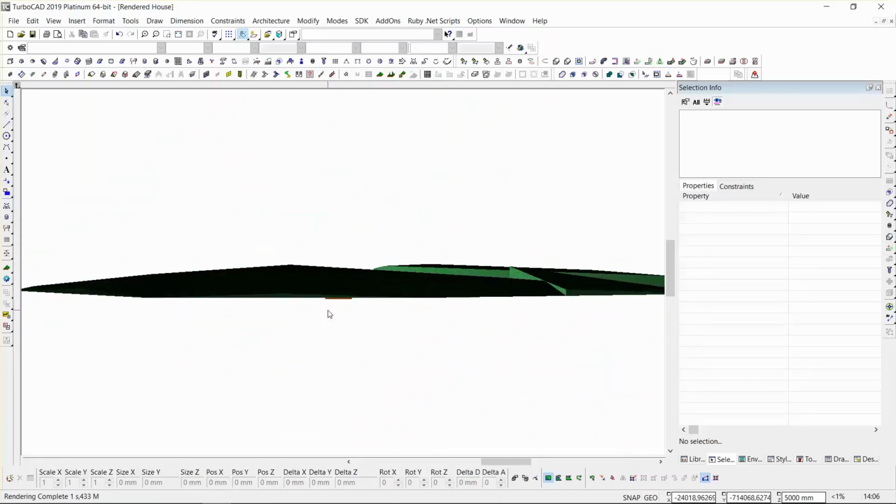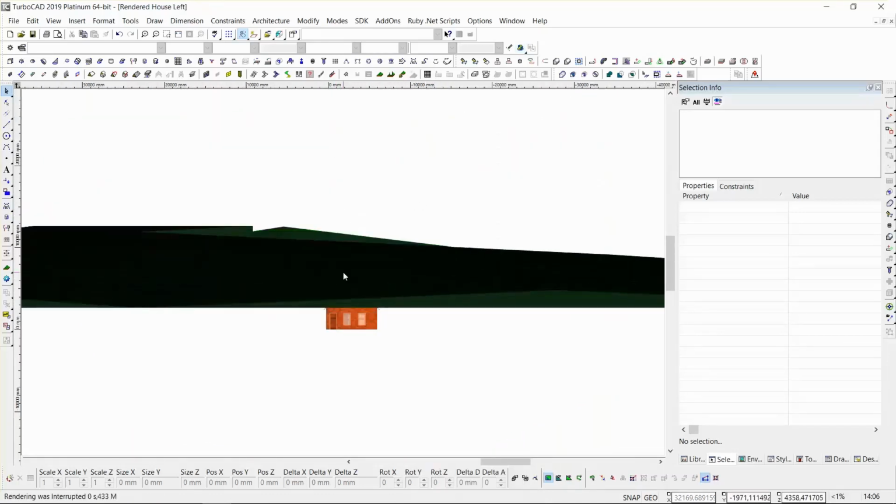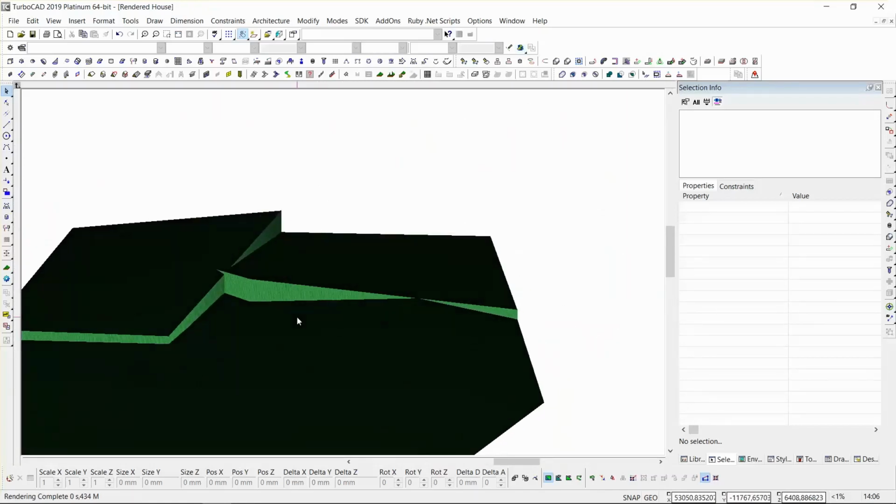Okay, you will get the idea. That will probably give you your levels, because you will have a 0 level. You can put a line on a left view or whatever, and you can get a section through that. You need to get a 0 line, and normally it is at your highest point unless you want to excavate. Okay. Alright, so does that answer your question as well?